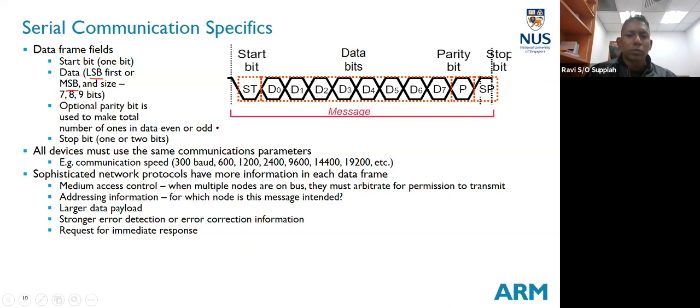Okay, the clocks being out of phase is not an issue, because as long as it is able to detect the start bit, the hardware internally will know when to sample next. All right, so you will know that once I detect the start bit, at what time interval later I need to sample again. So it will sort of readjust based on the arrival of the start bit.